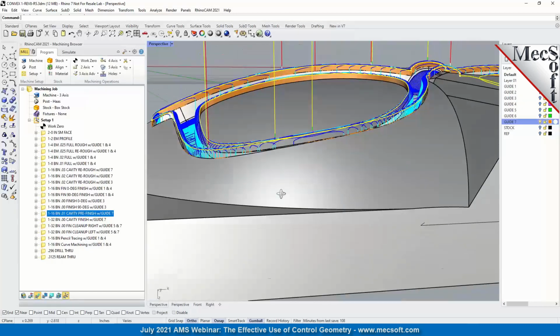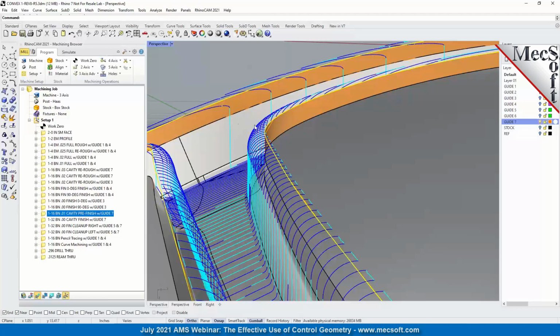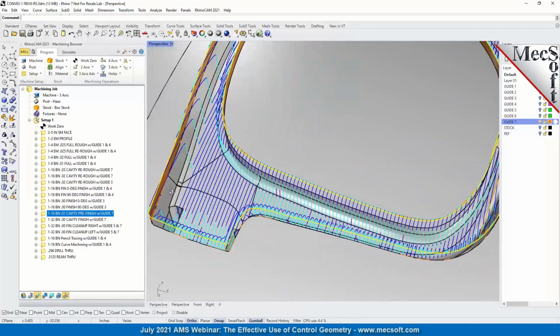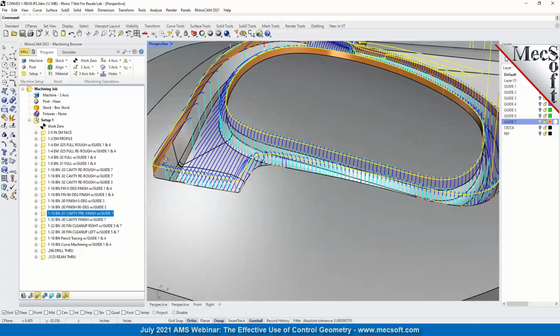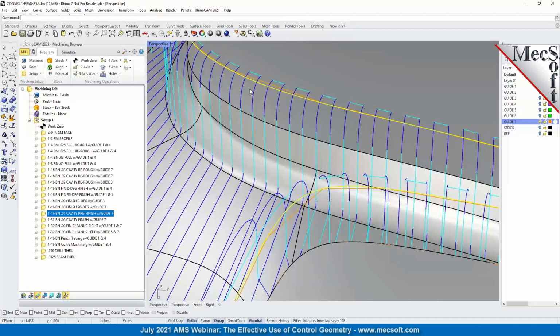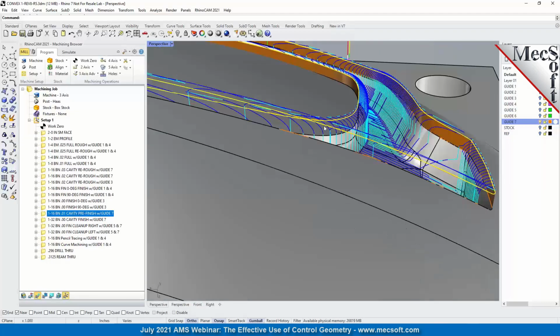Again, this is this surface that they added. They extruded the parting line up so that when they start cutting the finishing passes on the cavity, you'll see that it just goes right past the parting line on up and over the surface. And you'll see the rolling that I'm talking about right here.